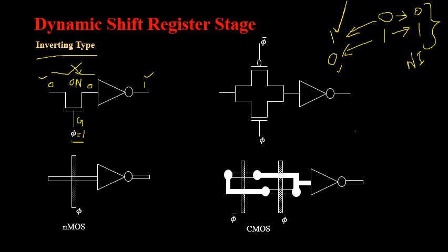If I want, I can check with the application of the input as 1. I will assume this signal as equal to 1 state itself, so the clock signal is still equal to 1, which has turned on the NMOSFET transistor, which is behaving like a closed switch. The applied input is equal to logical 1 state.